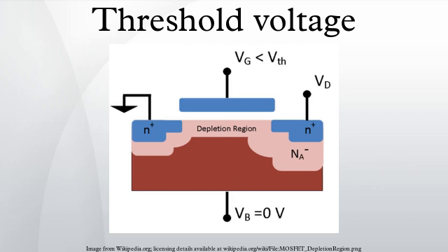The threshold voltage, commonly abbreviated as VTH or VGS(th), of a field effect transistor is the minimum gate-to-source voltage differential that is needed to create a conducting path between the source and drain terminals. At gate-to-source voltages above the threshold voltage but still below saturation or VDS, the transistor is in its linear region, also known as ohmic mode, where it behaves like a voltage-controlled variable resistor.